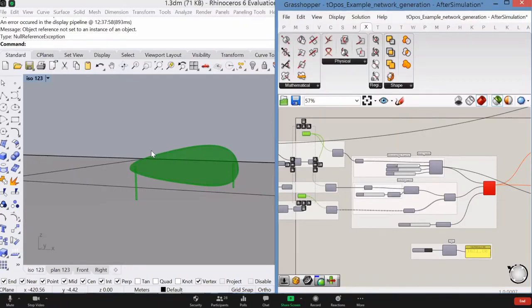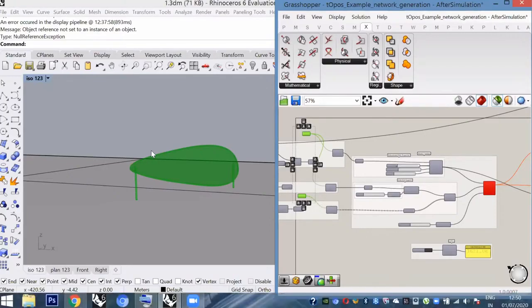Last night we tried to extrude the columns overpassing the slab, just having an intersection with this angular slab. But finally, again, we had the same error that we had when our column extrusions were exactly intersecting until the slab. And I would say that the thickness of the slab also needs to be larger.